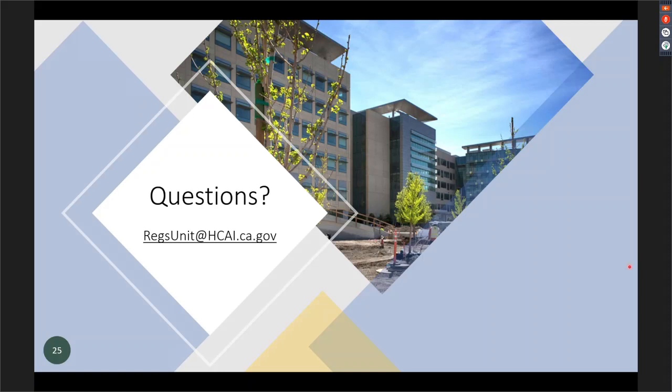Actually, if you're changing the drawings by code, you have to stamp and sign the drawings, period. Again, if you're answering an RFI and just providing a sketch or a picture to the contractor to answer it, no, you don't need to stamp and sign that. If you're converting it to an NMA or an ACD, both of those are signifying that there's a change to the drawings, and those do require a stamp and signature. Again, that's nothing that we're adding new. That's always been in the code for years.